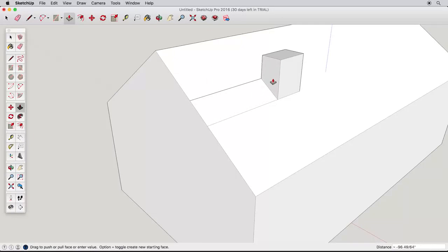By pulling across the roof surface, extra edges have been created, but these are easily erased. Any lines drawn across coplanar surfaces can be erased to form one larger surface. We call this healing the surface. Use the eraser and erase these two extra edges.